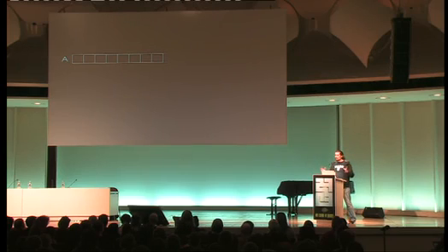So from a more theoretical point of view, what's the programming model? You have the A register, the accumulator. It stores everything and it transfers everything. Whenever you handle data, whenever you do arithmetic and logic, it goes through your single A register.